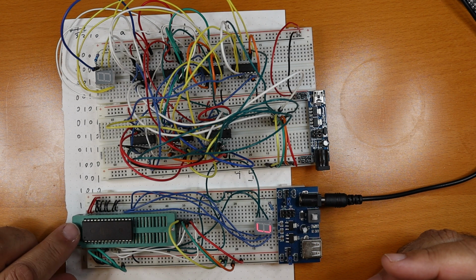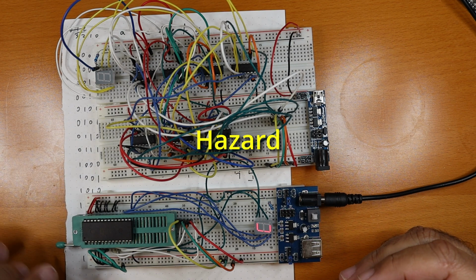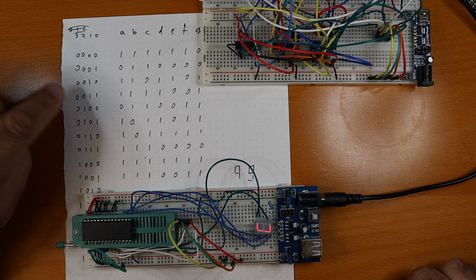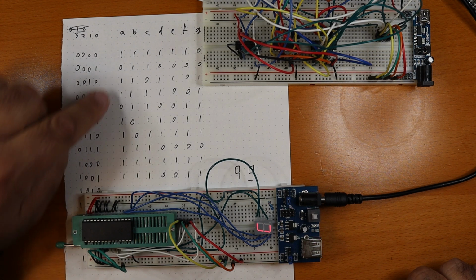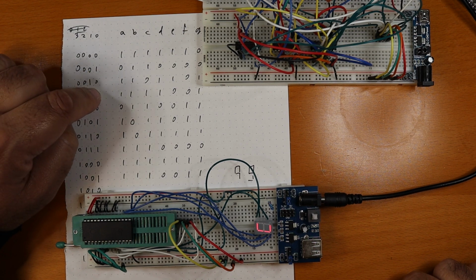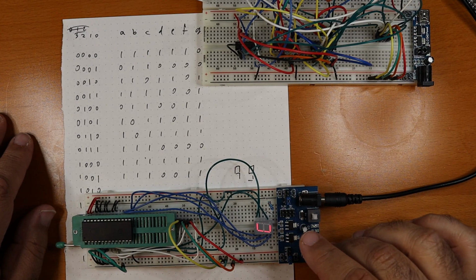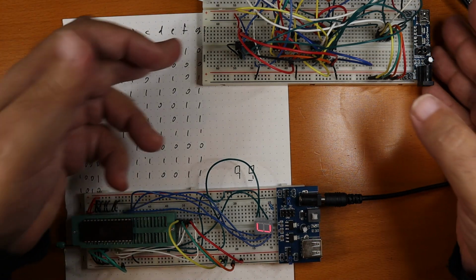Another downside of the ROM method is something called hazards, which I have not talked about. Very briefly, a hazard is when you have a single bit change, for example, from here to here, that goes from 1 to 1, but because it's covered by different logic sets, there's an interim 0, and that can cause problems.